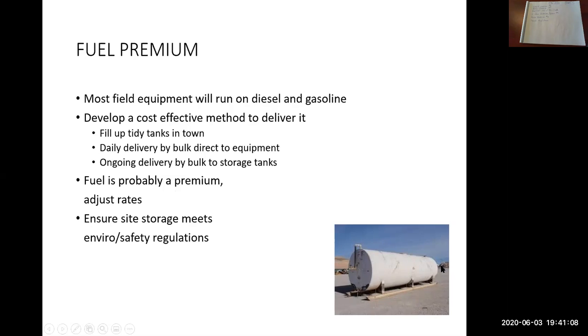You need a containment berm that'll hold, I believe, 110% of the volume of the tank, so that if it was completely filled and the bottom ruptured somehow, all of the fuel would be contained in the containment area. It wouldn't come out and start flowing downhill towards a creek or something.